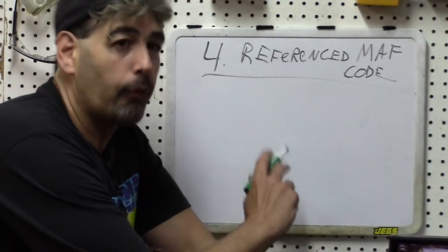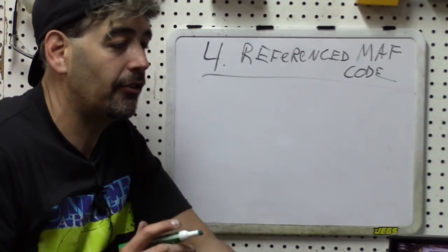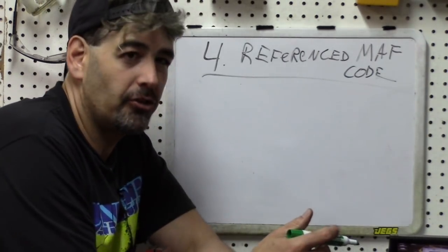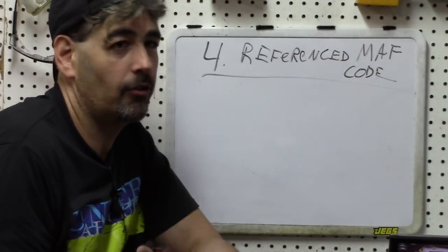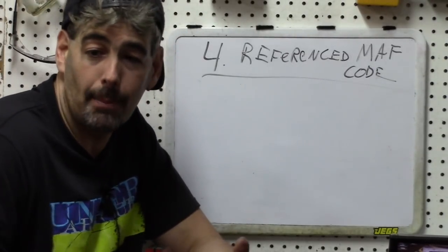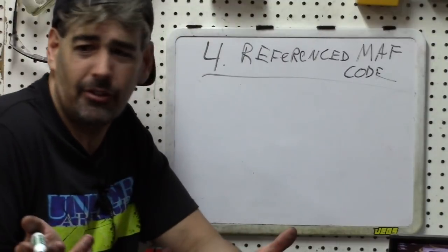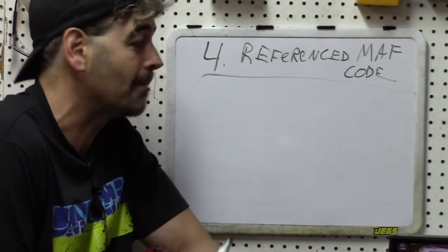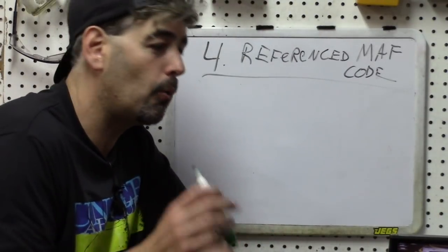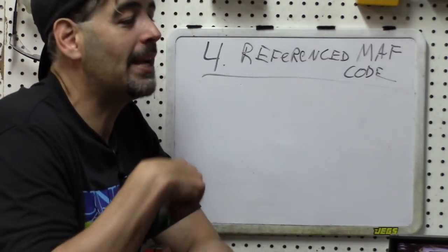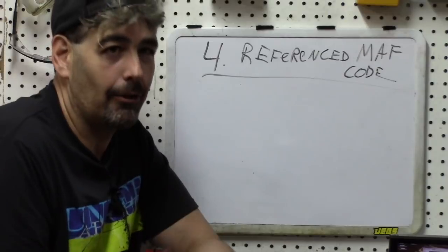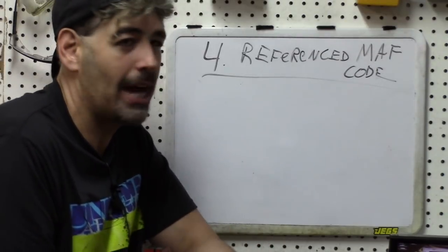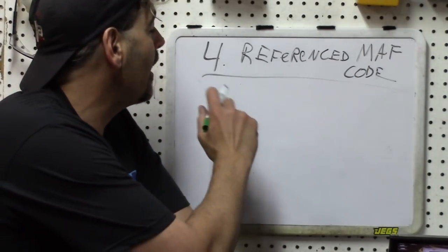They've generally avoided doing the mass airflow sensor as one of their parts changing experiments because the MAF sensor tends to be very expensive on a lot of models. I know on my Trans Am here, I think it's like $400 or something. So the problem is they don't want to replace the MAF sensor because they want to replace all the cheaper parts first. Then eventually they get around to the idea, usually from the chat rooms and forums, that their lean condition, which would be an 0171 or 4, or maybe even a rich condition, must be because of inaccurate induction measurement with the incoming air.